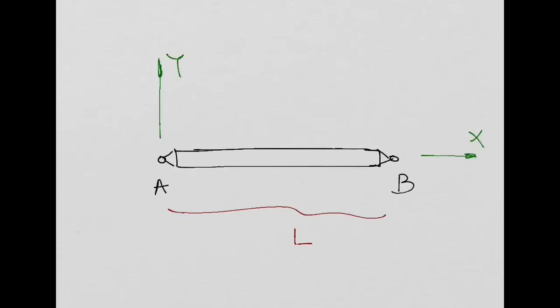And so basically what I'm doing is I'm building the free body diagram of this strut. So I need to include now the reactions. Which reactions am I going to have? Well, I'm going to have here By, Bx. Agree with me? So don't forget, the strut is hinged at point A and point B. So same thing at point A, I will have Ax and Ay. You all agree with me? These are the reactions I have in a strut.